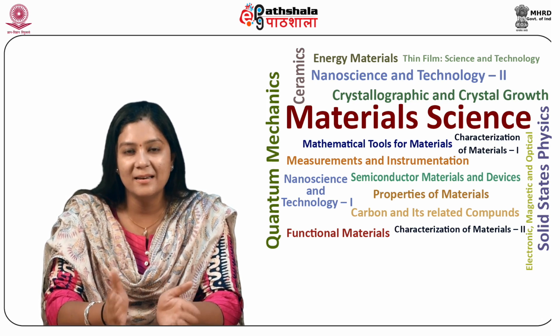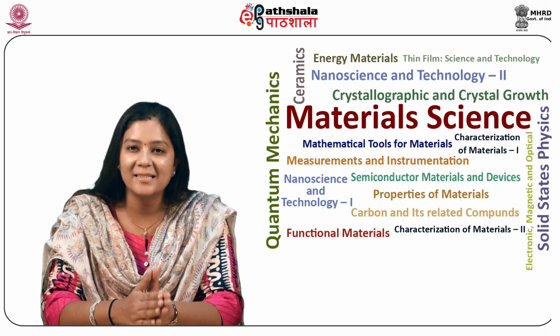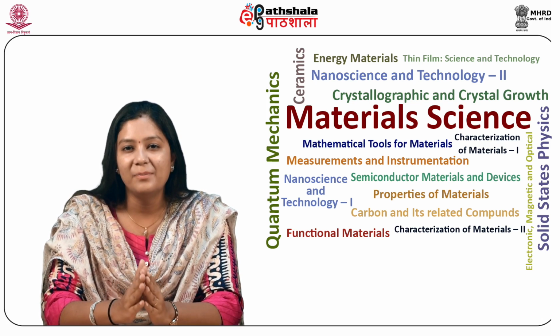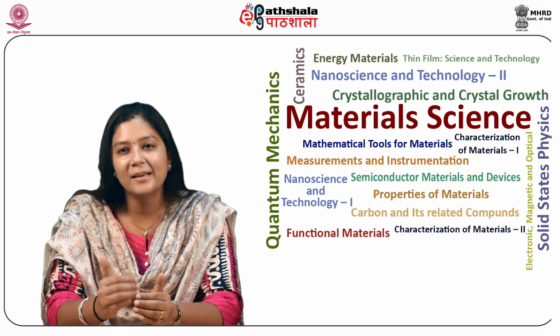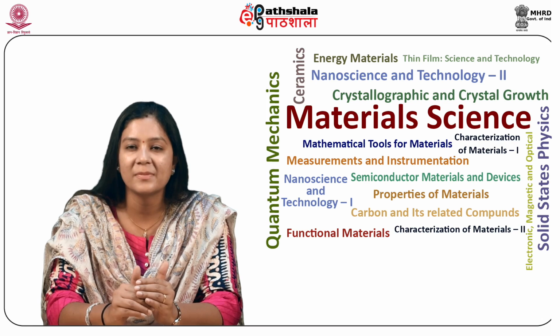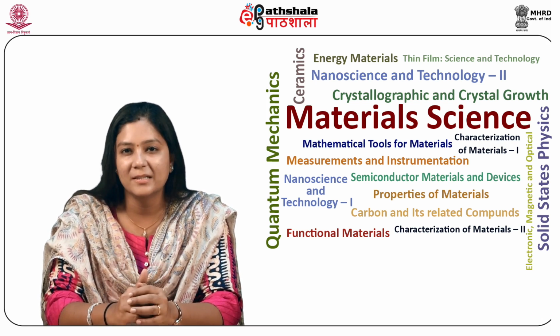One of the methods to achieve etching is dry reactive ion etching, or DRIE. It makes use of chemically reactive plasma to remove materials deposited on the surface. This gaseous form of etching is mainly used for obtaining highly anisotropic etching, a disadvantage of the wet etching process.